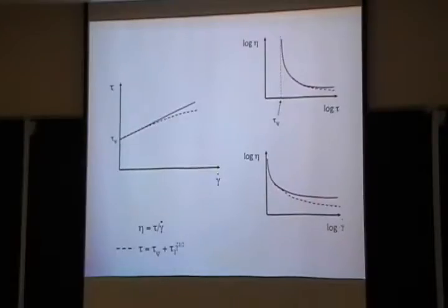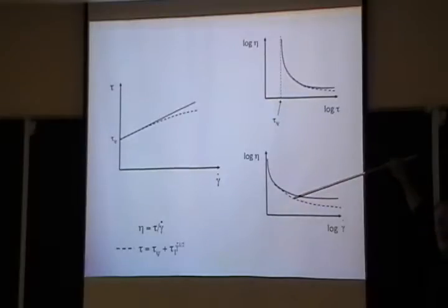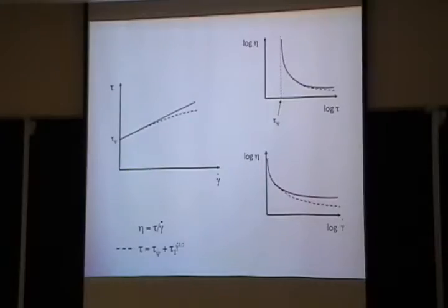Now, a shear thinning fluid, therefore, let's say one of these power law versions, would look like this. Now, the viscosity is not constant. And most liquids are either Newtonian or shear thinning. And they have made shear thinning by design because that's what you like. But there are some crazy liquids that are not shear thinning and in fact shear thickening. So that means the viscosity actually goes up as you shear harder. And that's maybe a good candidate for walking, right? I mean, wouldn't that be kind of cool?